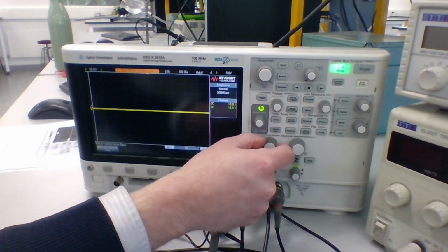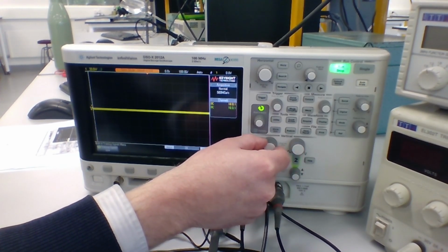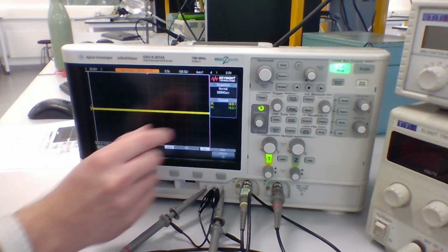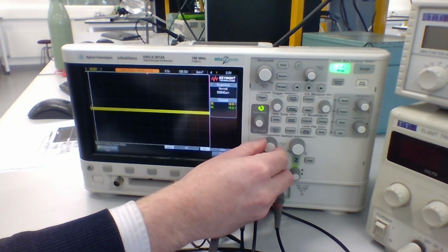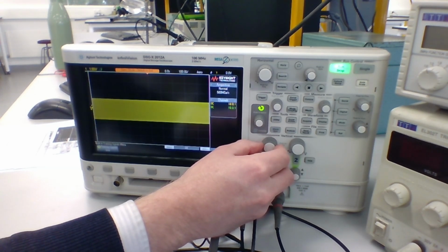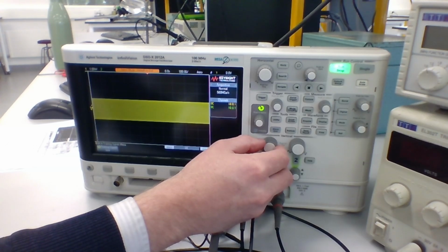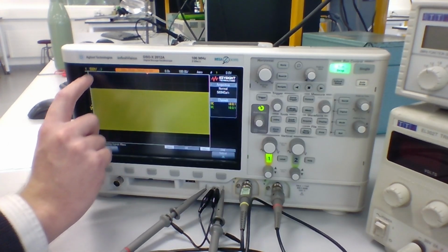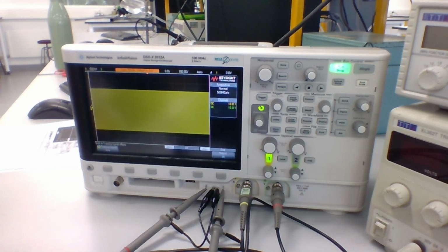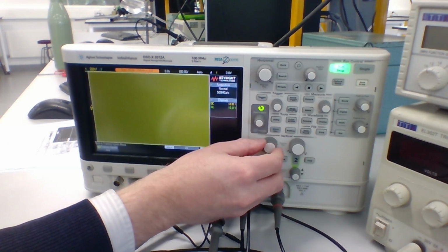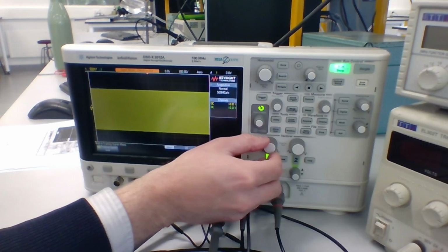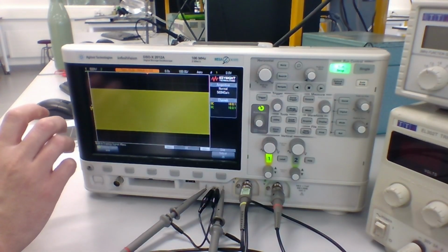So we can turn this dial to change that scale. If I turn it once, that scale changes to 20 volts per division. And we can see there's a bit of something on the screen. If I keep turning that, I'll start to see more and more going on. What we want to do is, following the instructions, set this to be 500 millivolts per division, which is what we have up top here. If you set that any smaller, what we're seeing goes off the screen a bit. So that's about as accurate as we can get.